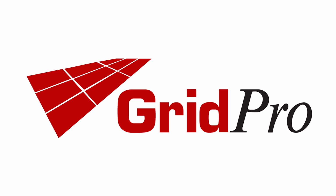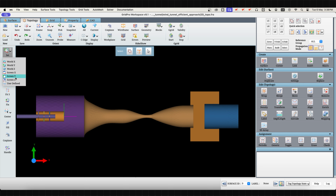We will create topology for this geometry in two sections. In today's video, we'll build a two-dimensional wireframe and revolve it to capture the axisymmetric domain of the CD nozzle, test section, diffuser, and muffler. In the next video, we'll capture the shower head assembly using GridPro's whole topology generation tool. Let's get started with the 2D wireframe generation for the geometry.